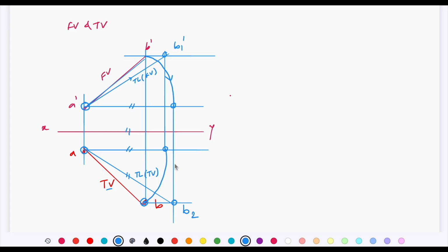And another way is, as it is representing true length, it is going to be the same in case of front view as well as top view. It is not going to change. So once you have got true length in top view, that is segment AB2, take length of AB2 in a compass, choose center A dash, and the locus that you have drawn through point B dash has intersection with that locus. The intersection point is again going to be B1 dash only. So either you can do that one, or conventionally you can rotate the top view and then project it vertically upward to have intersection with the locus of B dash. Both ways you can get the same point. So this is the first scenario when front view or top view has been already located.